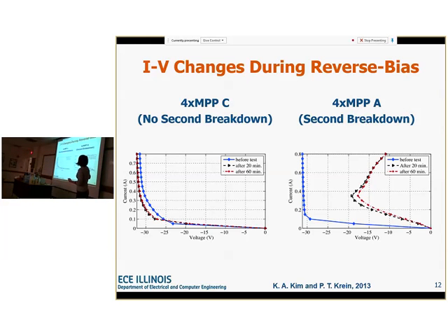And yes, it is going to draw less power, but it's all going through such a small point instead of being spread out that there's likely damage happening in that corner. So it's still more than it should be going through that small corner. So it's still damaging the cell, even though it's only that one cell, and it's a weak point in the cell. Does that follow, kind of?